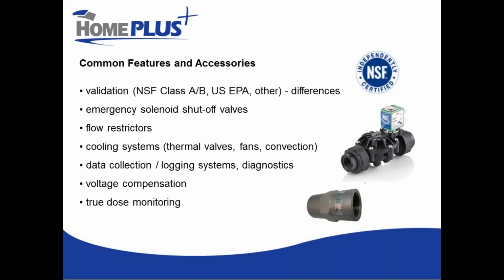Whenever you go over 30 gallons per minute, the NSF 55 Class A standard has no protocol for testing beyond 30 gallons per minute. So when you get up into that range, you will see devices certified under the US EPA UV disinfection guidance manual.